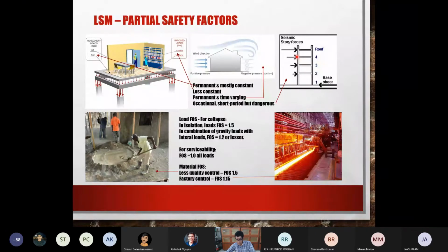It can cause damage. You know that in heavy earthquakes, buildings fall. Why do they fall? Because an earthquake usually acts from the bottom. It shakes the base of the building, and because the base is shaken, the building, which is at rest, starts moving with an acceleration. When an object at rest is subjected to a sudden acceleration, what kind of force is generated? Inertial force. So inertial forces develop in the structure, which are also forces, and they are caused by this seismic effect.